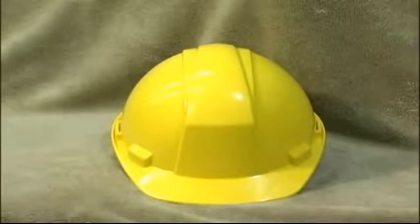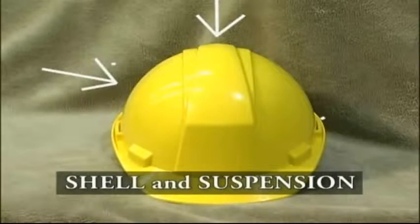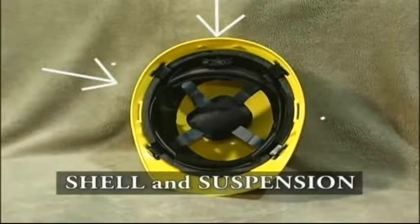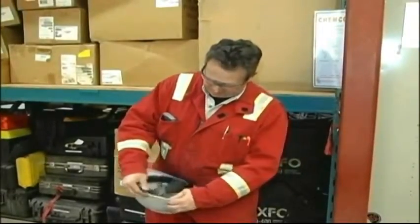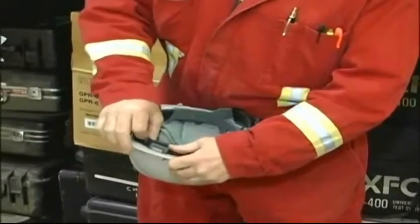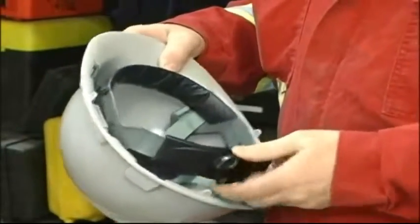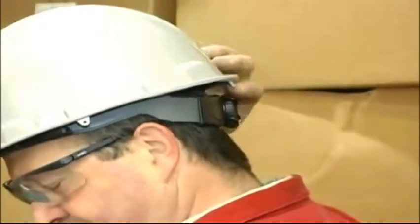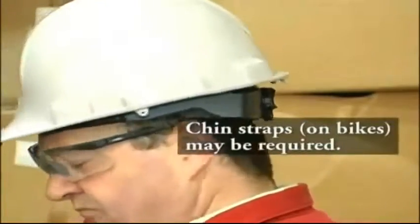Hard hats come in a number of styles, but all essentially consist of the same components. The crown or shell is designed to withstand impact and penetration, protecting your skull and your brain. It is important that the suspension be attached to the crown correctly. The suspension and headband, along with the shell, help to absorb, distribute, and/or deflect the impact, and keep the hard hat from being dislodged and falling off. On some sites, chin straps may be required.